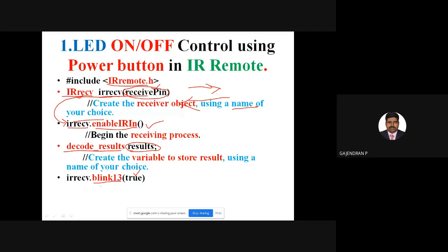At the same time, if you enable this option, you can't use the 13th pin for any other application while it receives, because while it receives, it will turn the device on and off. If you are using the same pin for any IO control, whenever you receive, it will disturb your output. That may lead to some accident. For that, if you use this option, please ignore the 13th pin. You should not use the 13th pin for any IO devices.